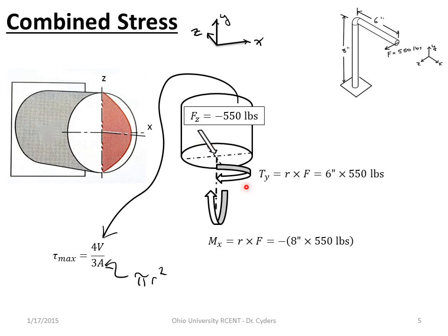So here at point A and then kind of across from point A, those 2 points, my transverse shear is going to be 0, but it's going to be constant in lines along the x-axis across the cross-section. And so that distribution is going to be parabolic, and the transverse shear then is going to be maximum along this x-axis. So we're going to have a maximum shear stress due to transverse shear here at B, and we're also going to have my maximum torsional stress, which is the same at A and B.